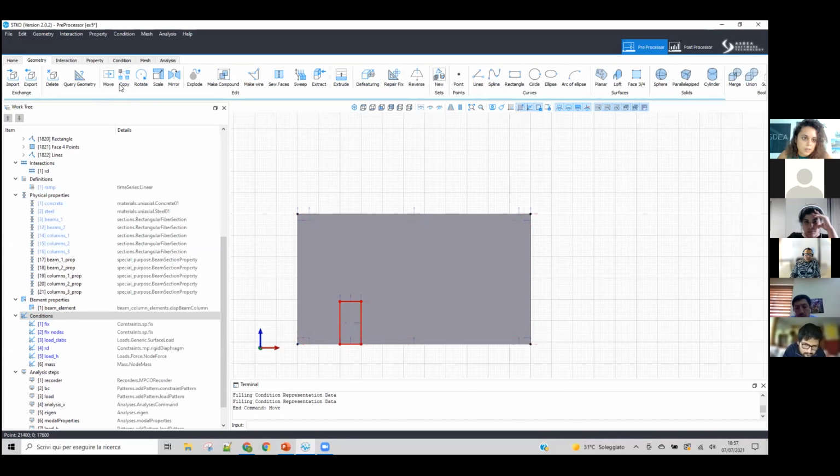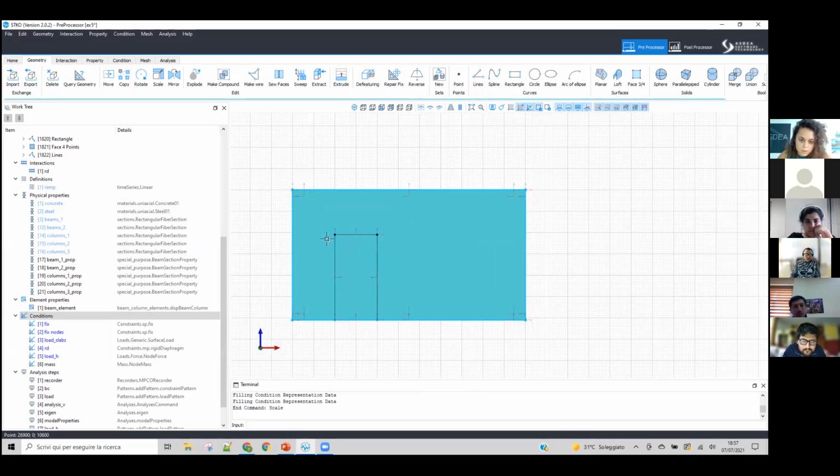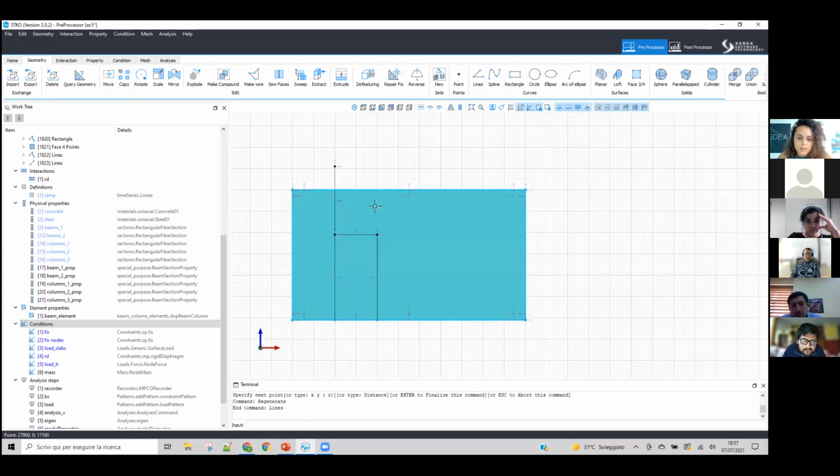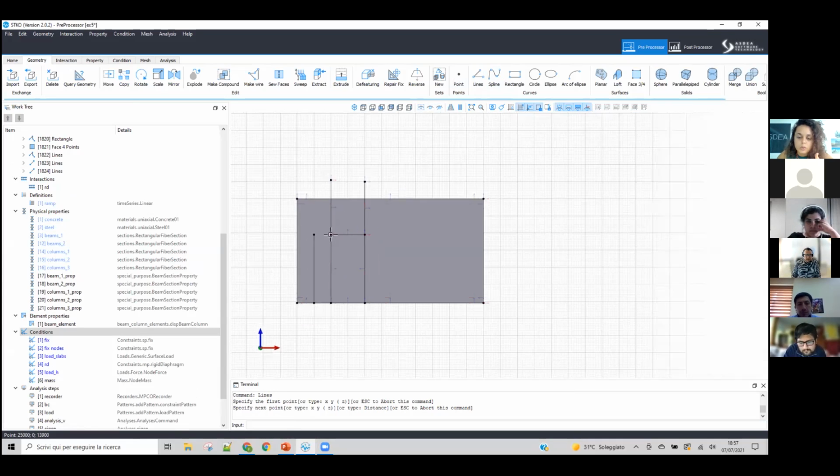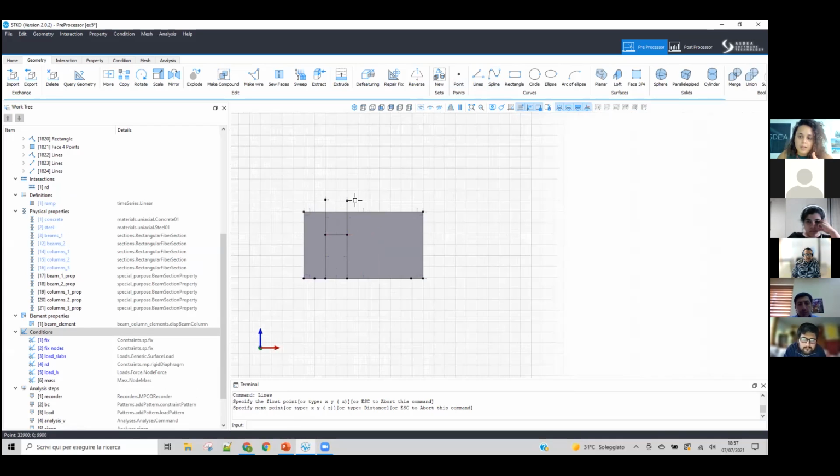Okay, just let's scale this. Okay, so this is your wall, this is your door. So you will have your elements discretized by these lines. The beam element that is actually, for example, representing the spandrel should not be aligned here and then offset in this section to the right, but should be aligned at the center of it. And then what you have is actually a frame.